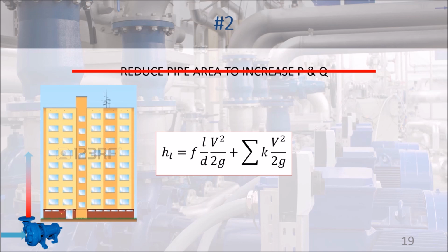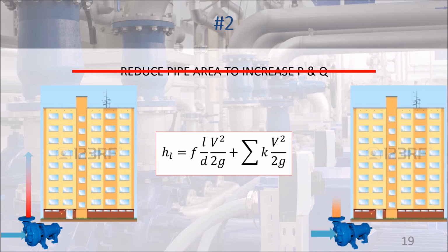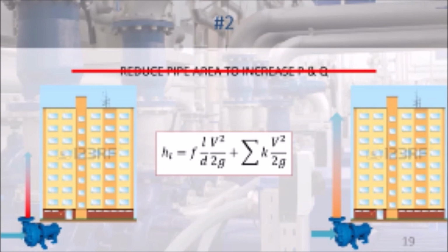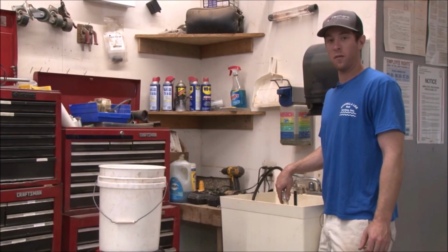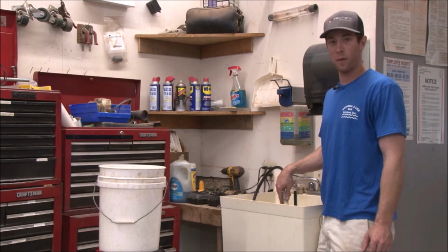If you replace with a smaller diameter pipe, the friction loss in the new narrow pipe will be larger. The correct procedure is to increase pipe diameter or install another pipe in parallel to the existing one. This allows the liquid to flow smoothly like a car on a highway. So, part 2 here is water flow as it varies with pipe size.